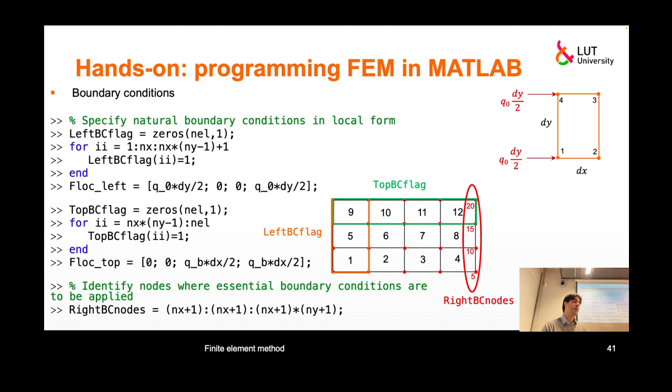And that's not only me, but if you will be using some commercial finite element codes and you want to apply heat flux, usually you apply it on faces of elements. Of course, eventually there will be contributions in the right-hand side related to each node, but it's more physical to think about it associated with a face of an element. So I want to identify elements on which the left boundary condition and the top boundary condition come.